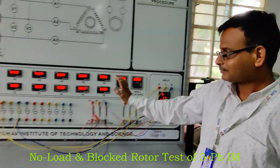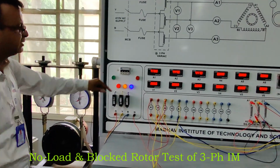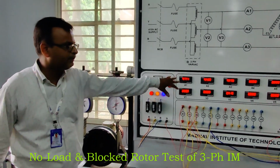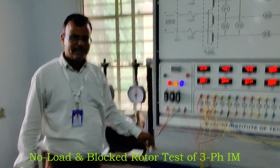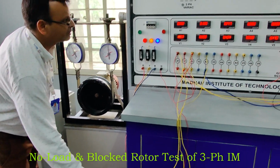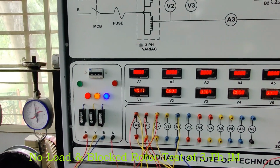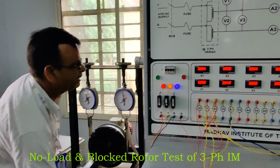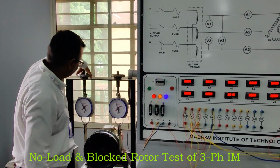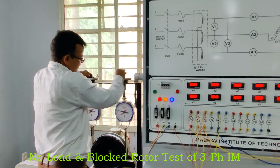So these are the readings for the block rotor test. It means in that test you have to set its rated current. In the no-load test we have to set the rated voltage. Then gradually reduce the current up to 0 ampere, and the motor load is reducing.